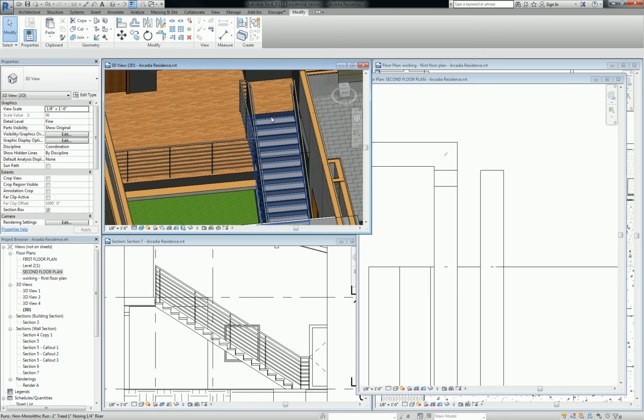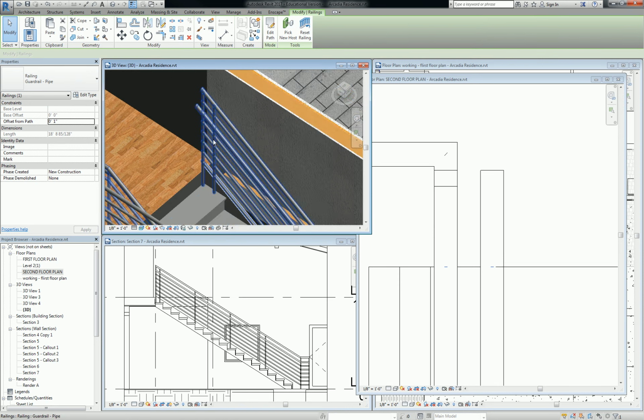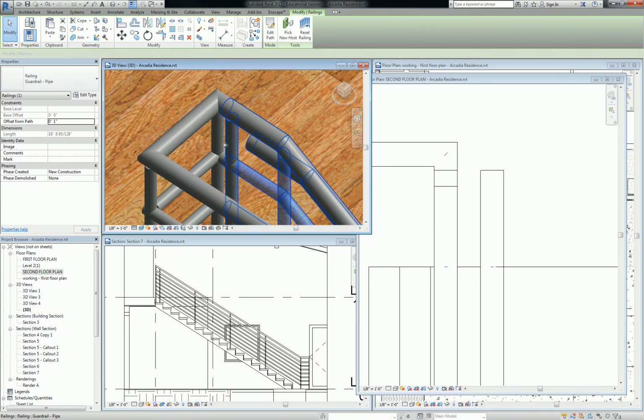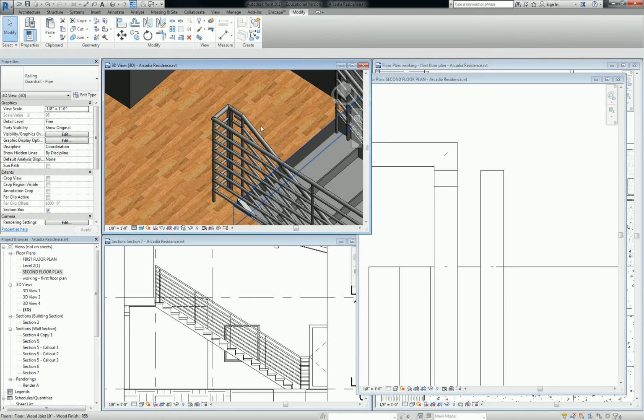Although, I will admit, knowing exactly how you want the railing to be detailed and being able to create a simple enough parametric condition for everyone to create anything is incredibly difficult to do. So this actually isn't too bad. And if you needed to, you just go into your elevation and do some drafting lines over top of it and cover it up. As far as the BIM side of it, then you end up with extra balusters.